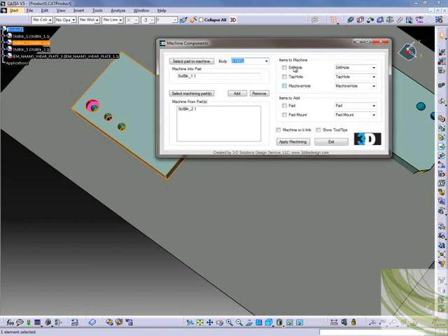We'll pop over here and we're just going to remove the drill holes, which are the dowels, and the tap holes. This block is not machined down in, so we don't need to do machine hole, and we don't have any adds. So we select those two items. We have options down here to machine without a link if you should want to do that, and then your tooltips. But once we pick the block and pick the items we want to do, we just hit apply machining.